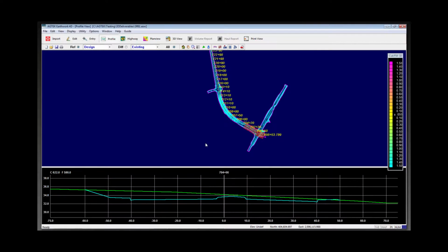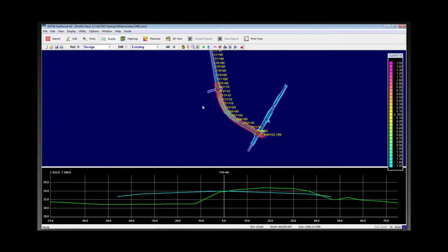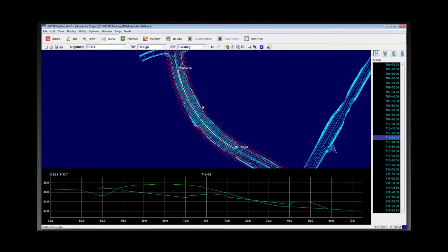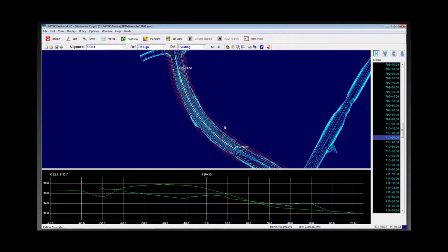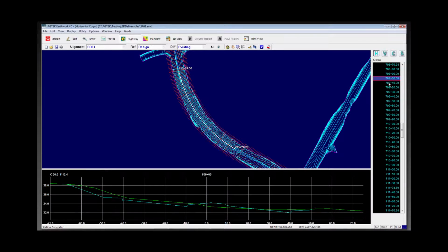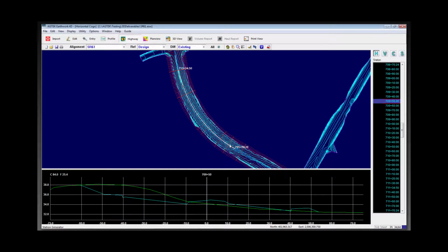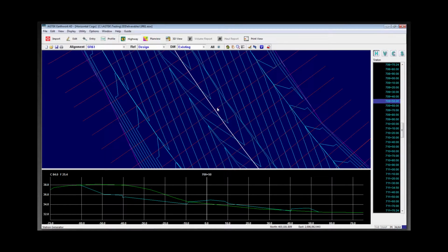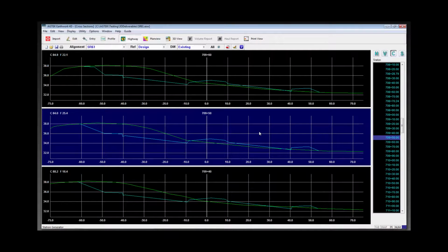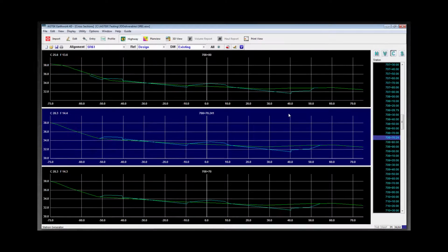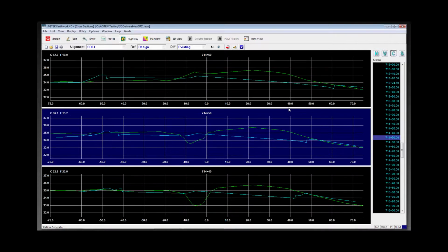And then when I choose OK, it goes through and you can see it creating cross sections. And it's doing it every 5 feet, probably because of the way I imported, or when I created the surface I had it at 10 feet. So then if you look here, you can view these cross sections this way. You can kind of tag along here, and it's highlighting the cross section you're on by this little flashing dot here. And then you can also view cross sections this way, where you just hit the C button for cross sections, and then you can scroll up and down or scroll this way and view the cross sections.